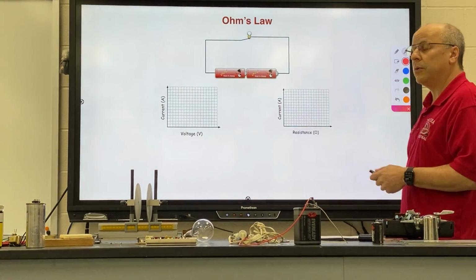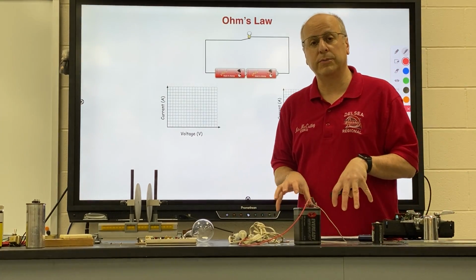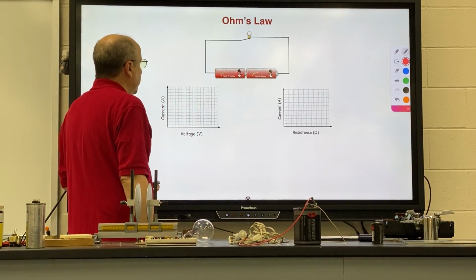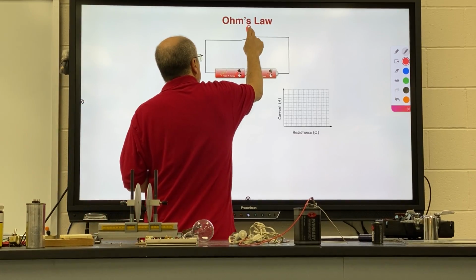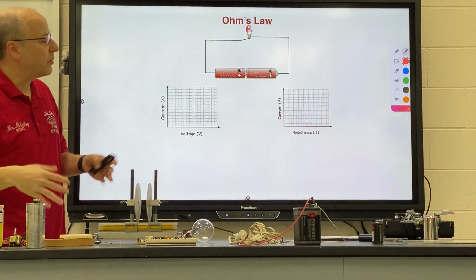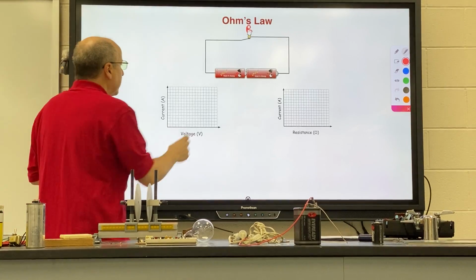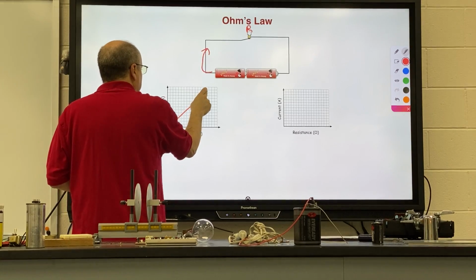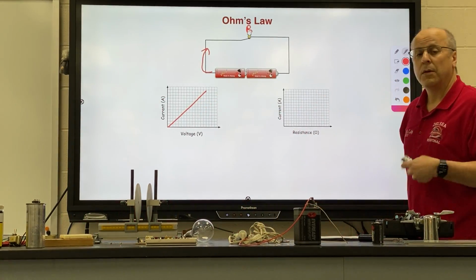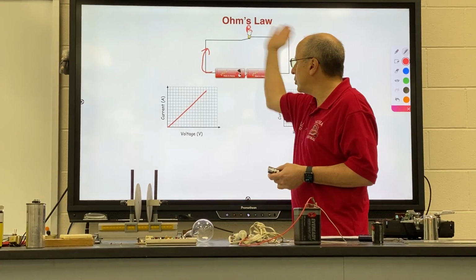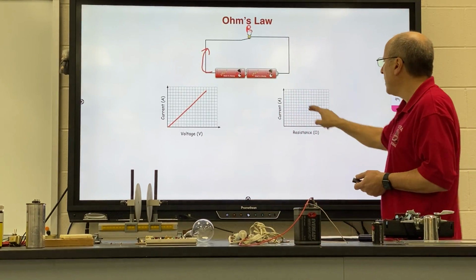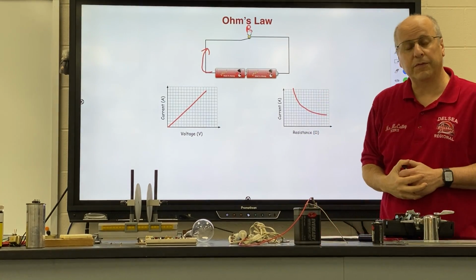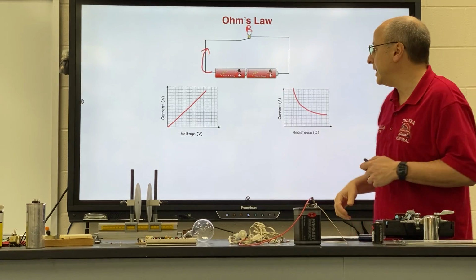Then we had Ohm's Law, which links together our terms of voltage, current, and resistance. Voltage again comes from the battery. The resistance is going to come from either your light bulb or your speaker or whatever you're powering. And then to find the current, you look at the relationship between current and voltage. More voltage will be able to push more charges through your circuit, and more resistance will inhibit the flow of current. So that will be an inverse relationship.